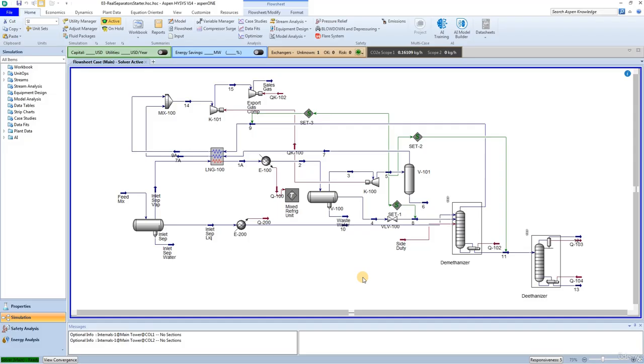Task 1. Specifying carryover effects. In real-world separators, separation is imperfect. Liquid can become entrained in the gas phase, and each liquid phase may include entrained gas or entrained droplets of the other liquid phase. In many cases, vessel internals are applied to reduce the carryover of entrained liquids or gases.